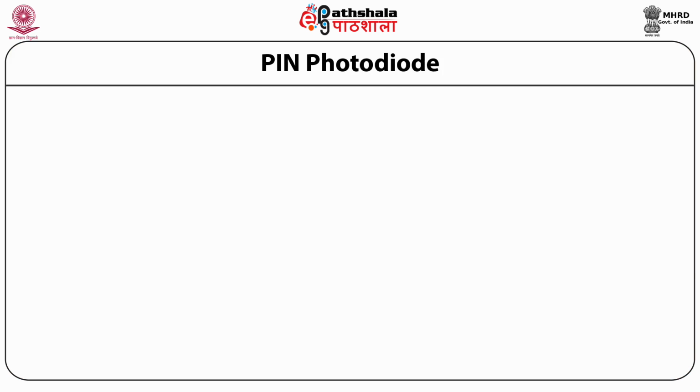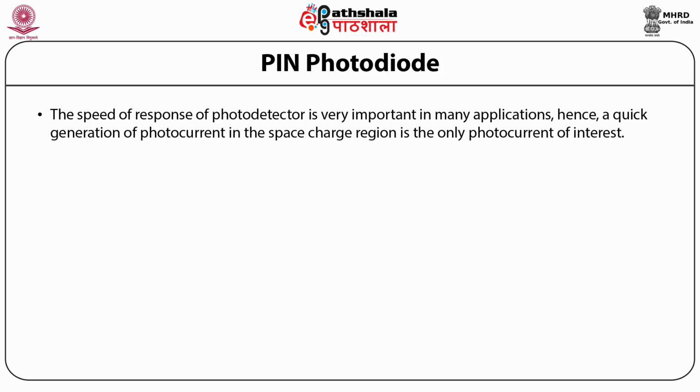So the diffusion components of photocurrent are referred to as the delayed photocurrent. Students, let us now discuss the PIN photodiode. The speed of response of a photodetector is very important in many applications. Hence, a quick generation of photocurrent in the space charge region is the only photocurrent of interest.